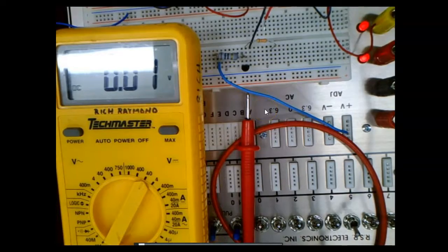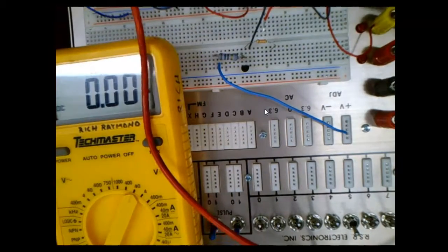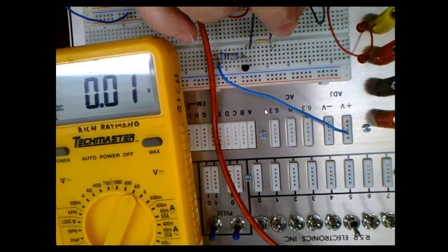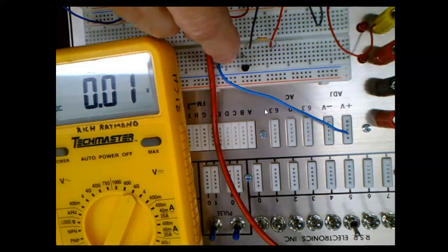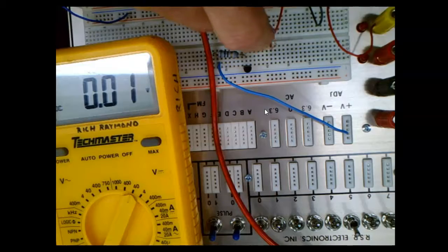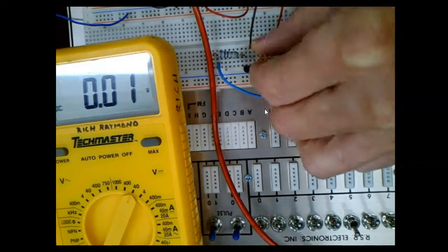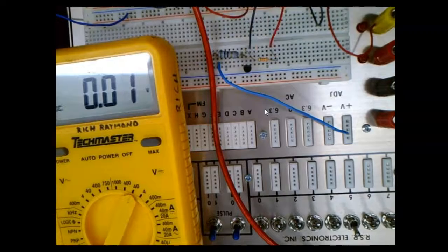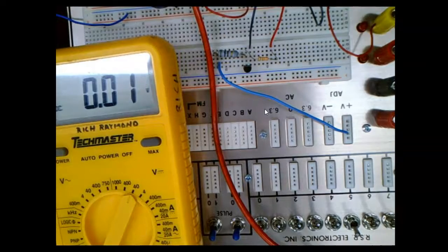Okay, so I'm going to come over here. The first thing I'm going to do is set my base current. So I got my voltmeter here. Where do I need to measure to set my base current? Here's my 100 ohm in the collector. The 33K is hooked up to the base. Here's my wiper off my pot, which you can't see, but this is coming down here. And here is R1 and here's R2. So this is 100 ohm. So where do I need to measure the 1.65 volts?